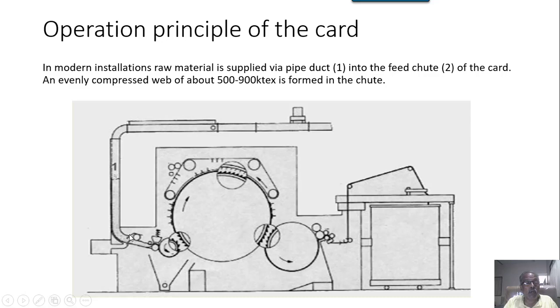All the manufacturers in today's situation, whether it is LMW, Rieter or Trützschler, are utilizing feed regulating mechanisms at this particular point. Partly I had thrown some light on the auto leveling, what takes place on carding, and what is the need, open loop, closed loop, etc. Where what is possible, we have discussed that.